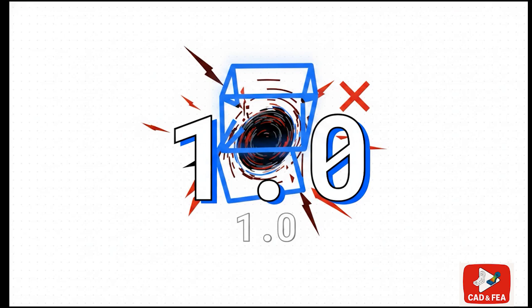Now, the key number to know here is 1.0. The determinant of that Jacobian matrix tells us exactly how much the element's volume changes during mapping. A mathematically flawless, perfect element has a Jacobian determinant of exactly 1.0. If the element is badly distorted, that number drops. And if it drops to 0, or even worse, goes negative, that means your 3D element has fatally turned inside out. If you try to send a geometry that exists in an inverted spatial dimension to your solver, well, it won't just fail, it'll throw an error that makes you question all of your career choices.